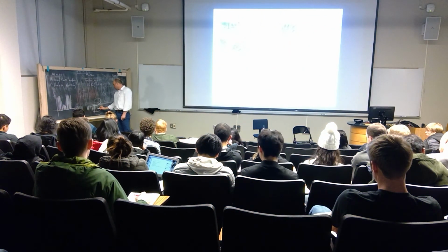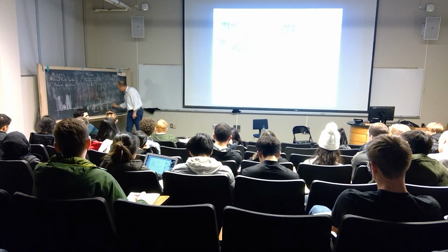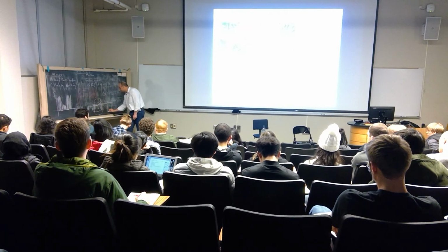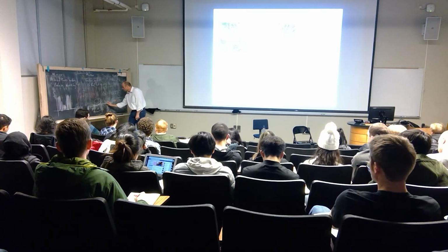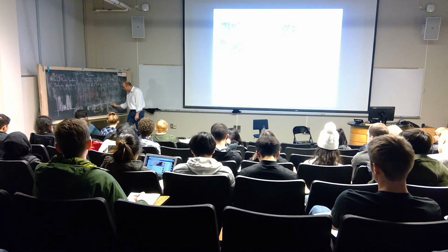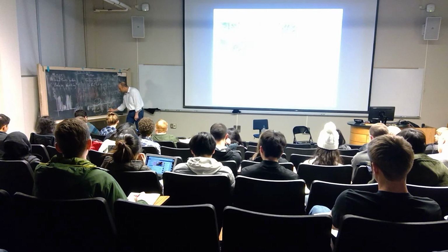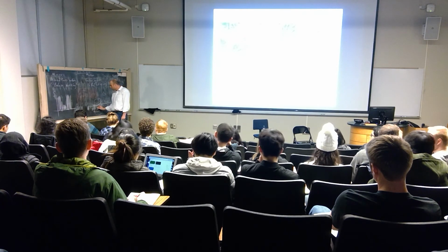So, you look at the stress element. The stress element says that it's subjected to this, right? And that's the plane of maximum, that's the direction of maximum tension. So if I'm looking at a stress element with rotation of 90 degrees, there's the direction of the maximum tensile stress. So my crack would start to grow, and then it would want to do that.